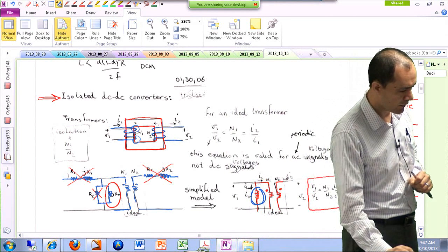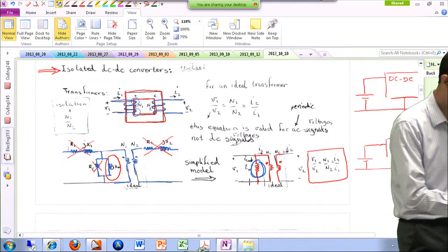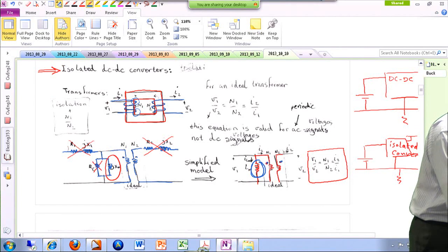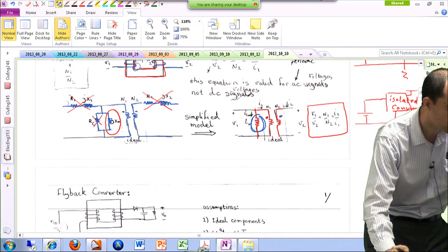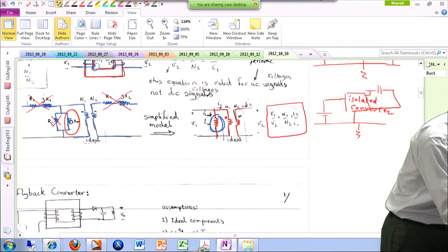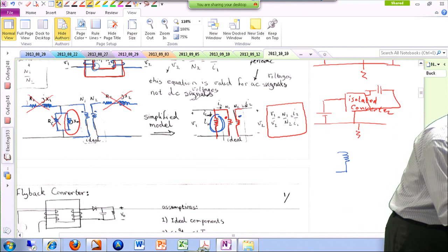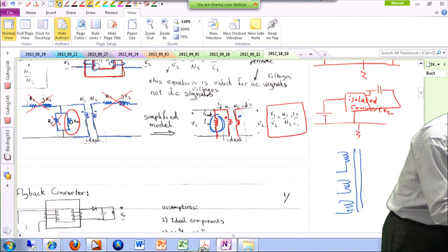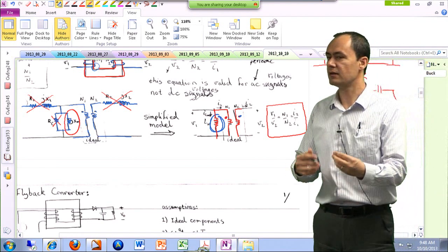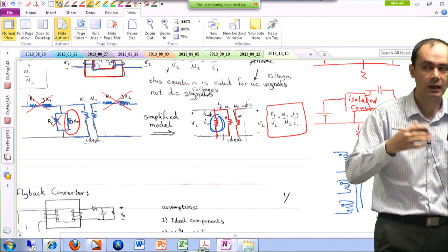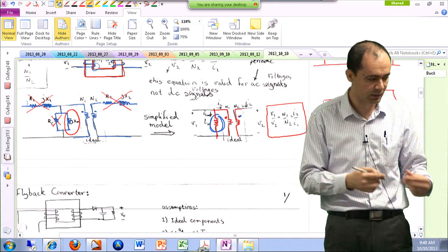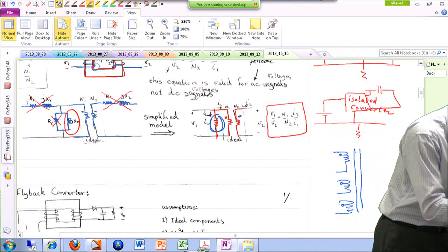All right, now please pay attention to these equations and these dots. It's very important to see where the dots are. And sometimes you may actually have more than two windings in your core. So let's say I have 3 windings, so I have this magnetic core where the flux of the 3 windings is linked, and I have chosen these to be my dotted nodes, looking at how the wiring has happened. Is it clockwise or counterclockwise, things like that.